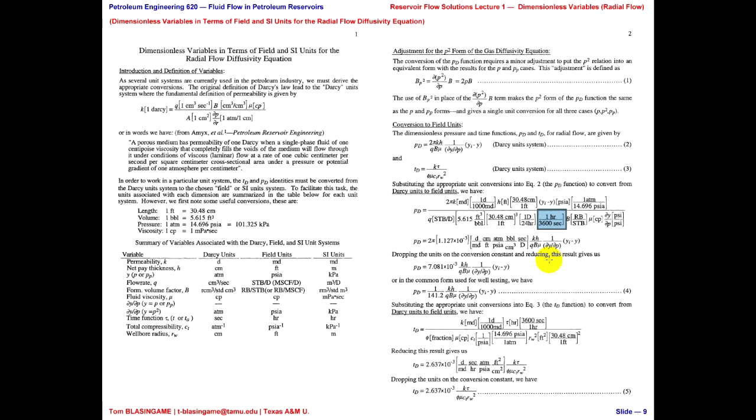When you're using a memory pressure gauge, how many points can you store? They come in increments of 1,000,000. So if you're going to measure pressure every second, you've got about 10 days. You want to give yourself some slack. So just be careful. I've seen people sample every second and then wonder why they ran out of memory on their memory gauge. Of course, the best thing to do is get a surface readout gauge, and then you can store everything, but that's okay. Very good, Gabe. You get a hug.